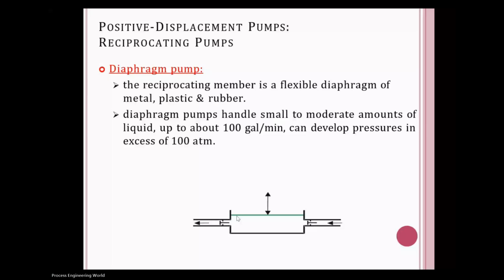Air operated double diaphragm. Right. So air operated double diaphragm means it is having a double diaphragm inside it. So it is operated based on air. Based on the discharge pressure of the air, your fluid is delivered, right? If you are having a highly flammable liquid, in that case, can you use an air operated double diaphragm or AODD pump? No, due to the oxygen content in it. Right. So there are certain limitations.